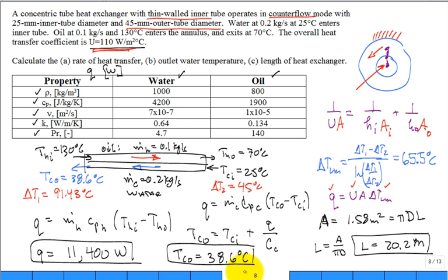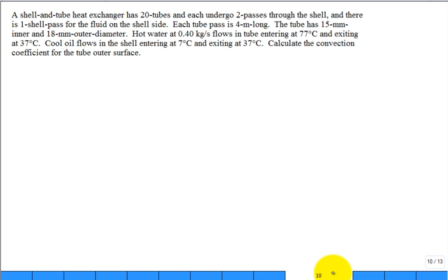When is the real benefit? It's typically when you only know the inlet temperatures, not any of the outlet temperatures, so you have to calculate it. Then you get into the guessing and iterating game with the log mean temperature difference, but with the effectiveness NTU method no iteration is required. But you almost have to see that to understand that.